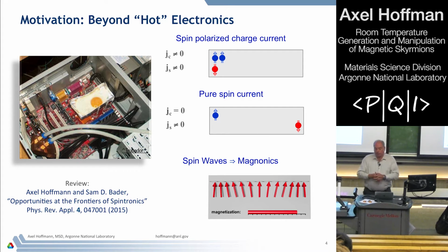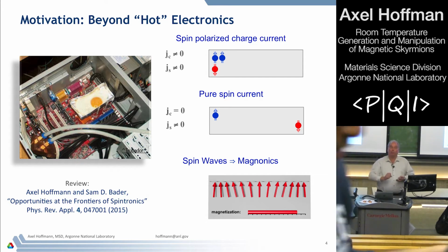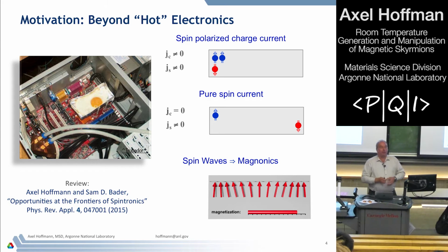And the main reason for this is that in most devices that you can think of, all the useful current goes through the bulk volume of your materials, and all the useless currents, that give rise to unwanted dissipation, go to the surface of your materials, and they leak out of your device. And so as you make things smaller, where the ratio of surface to volume becomes larger, the amount of leakage also becomes larger and becomes more and more of a problem.